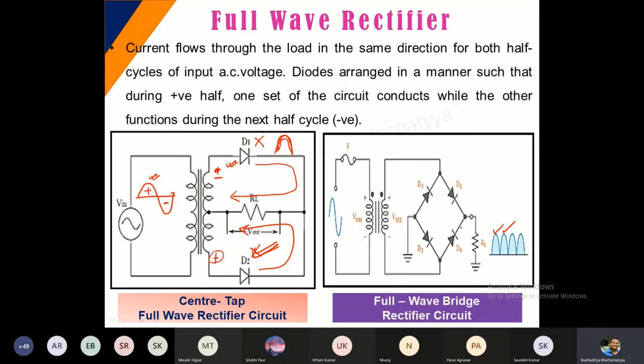So you can observe that for each positive and negative half cycle of the sinusoid, there is a uniformity in the way it is generated one after the other. You can see clearly that this is my first cycle, this is my second, this is my third, there is the fourth. If I shade this part red, this part was missing in half wave rectification, which has been added in the full wave rectification process.